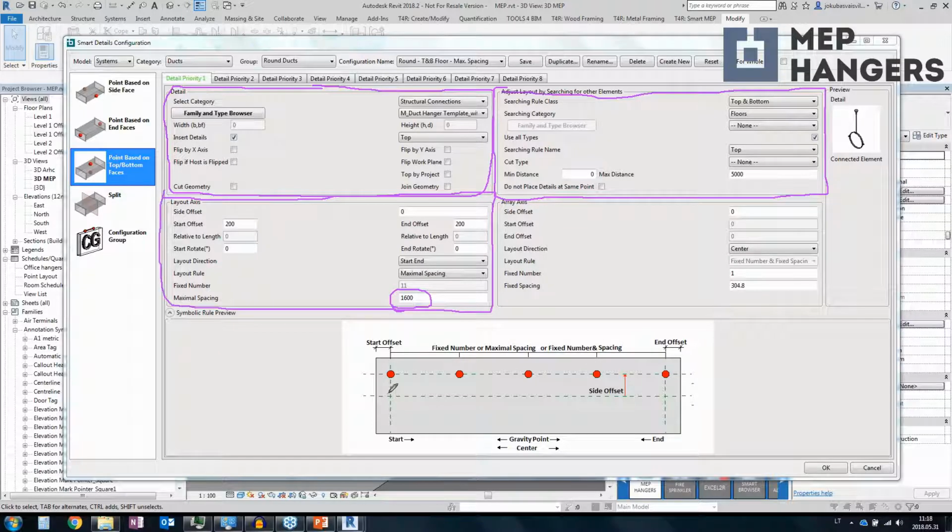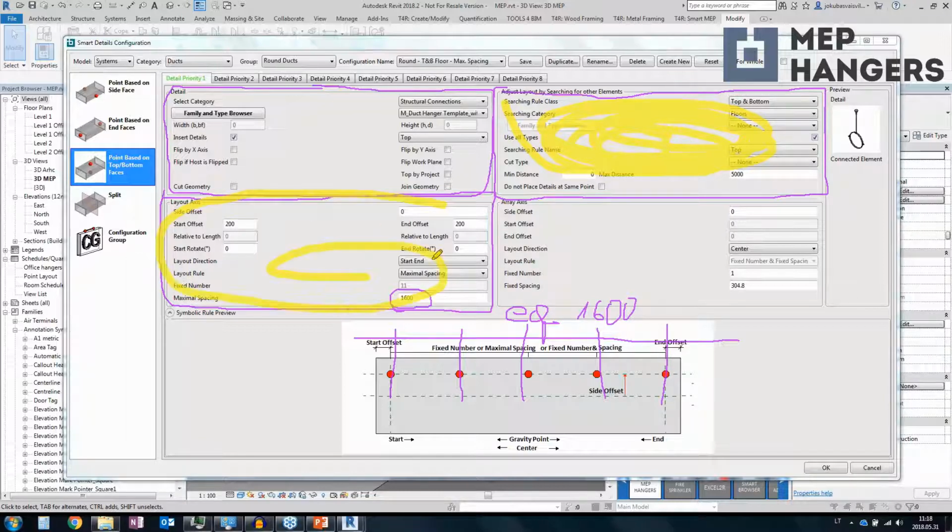And right here you're telling, okay, the first, the second, the third, the fourth, the fifth, and those are equal, and all of them are 1600 millimeters. So we're having several options. You can go either with this option, where you can choose where to connect, so the hanger will be placed exactly here, or you can work with distances between objects, like the maximum spanning distance.